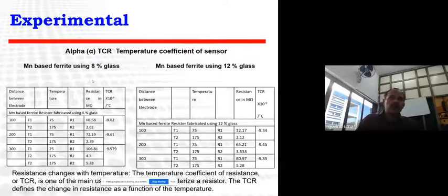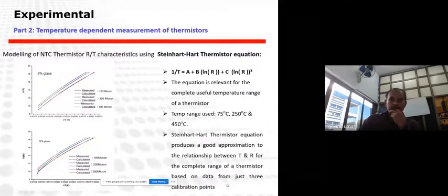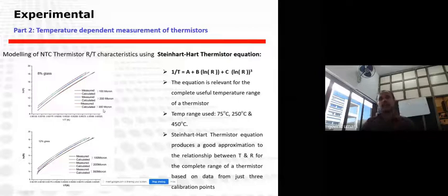So what we observe is that in this case, taking initial resistance at 75 degrees Celsius for 100 micron, and we take final temperature as 175 degrees Celsius to find out, we got TCR values around the same, in the range of -9.61. In both the cases, TCR remains in the same range. So we modeled this based on that value.